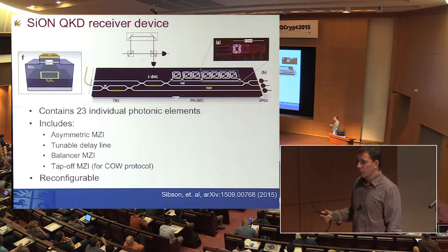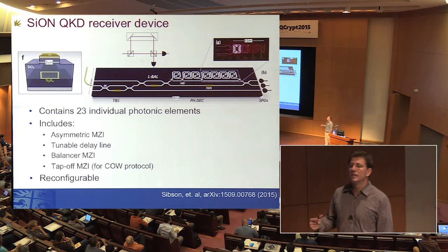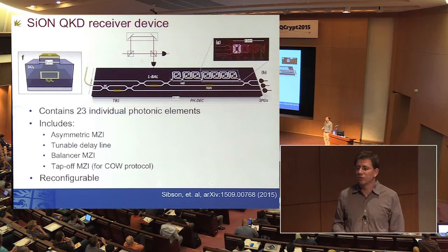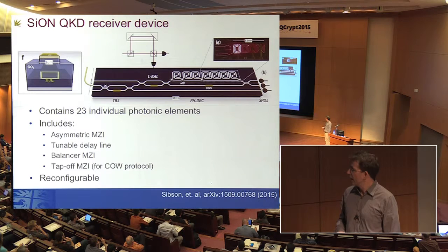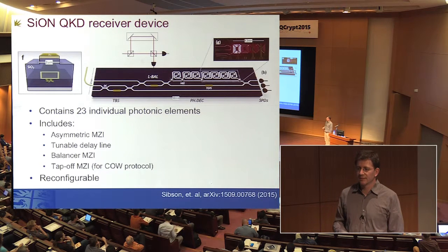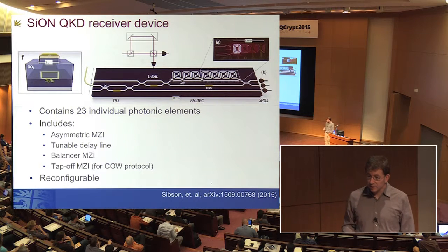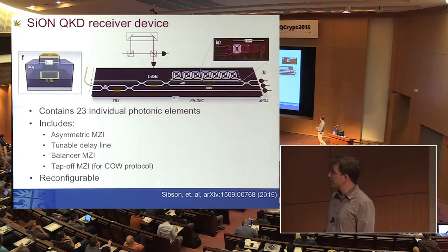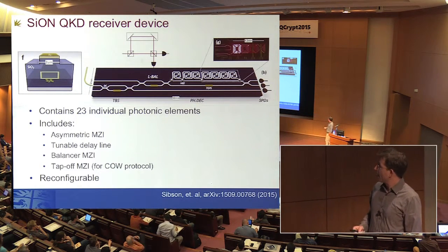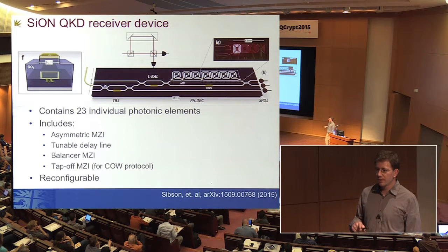And like I said, in the long term, we'd like to move to looking at whether on-chip-based detectors are possible. There's some work in silicon germanium detectors in silicon that might eventually lead to avalanche photodiodes in the silicon, fully integrated into silicon, which is very exciting. And then your second question was about on-chip isolators.